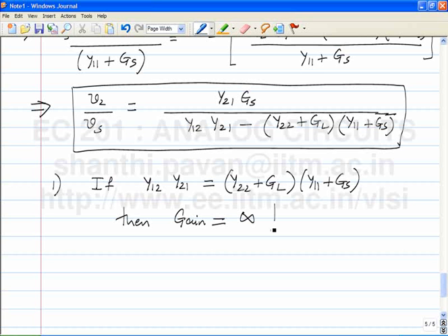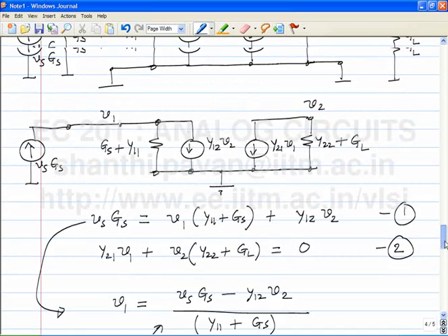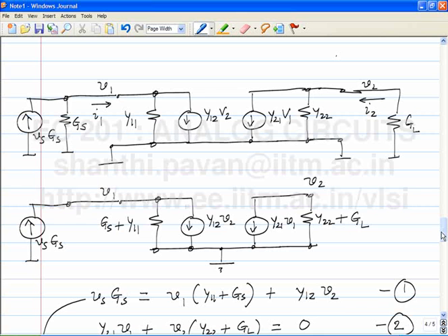Okay. This is output without input. In terms of Y parameters, can you now understand why this is happening? This is a 2-port. This is the input port, that is the output port. In a 2-port network, what is Y12 physically? What is the intuition behind, what does Y12 stand for? Y12 or H12 or Z12 or G12, they quantify, typically in an amplifier, if you whisper into the input, it must sound like somebody yelling from the output.